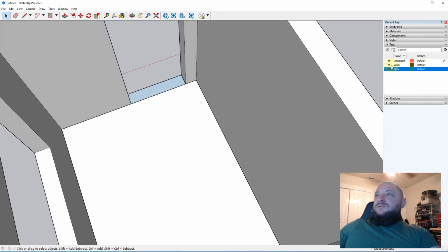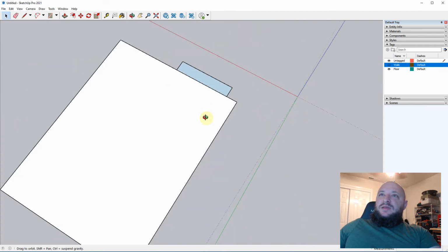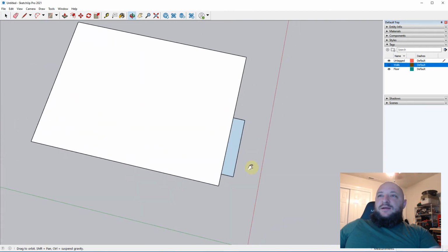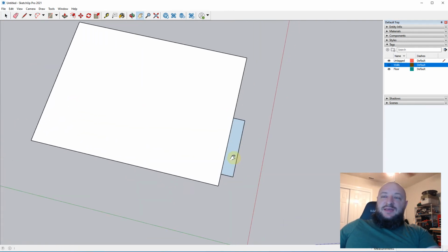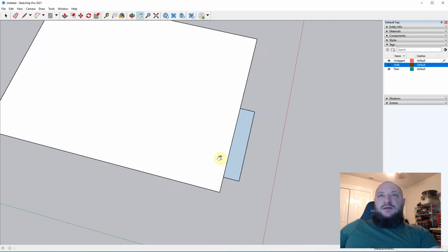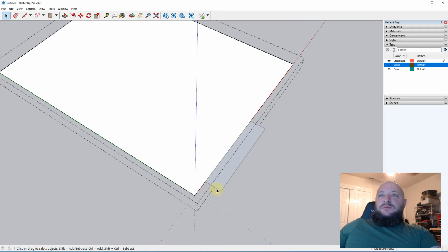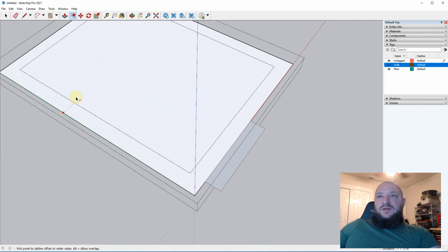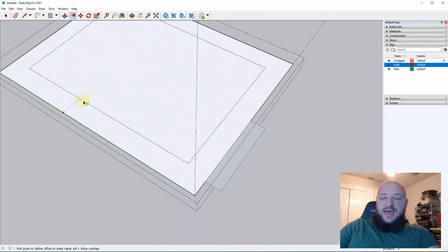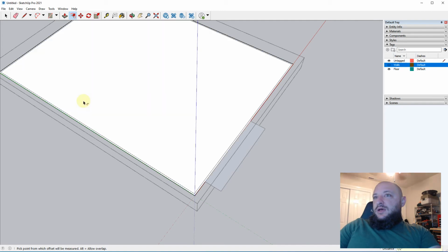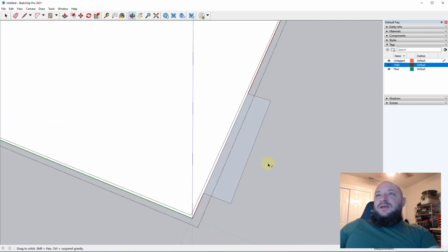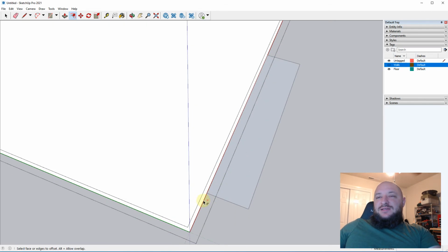And now I'm going to hide the walls. So what I've got now is the floor that's right here, and I've got this little space. This is just a reference for me to understand where the door space is. What I'm going to do is double click on this floor, then hover over it itself, and bring this in. I'm going to do a 1/2 inch, but this is a real simple way to add a baseboard to your project with like 0 effort. And so now you can see I've got this little lip right here, and I've got my reference spot.